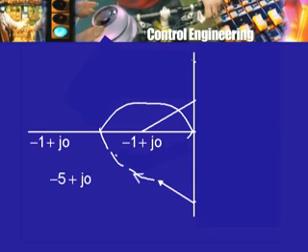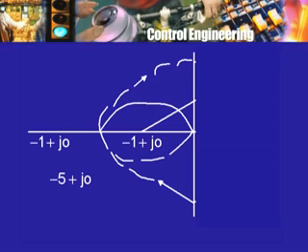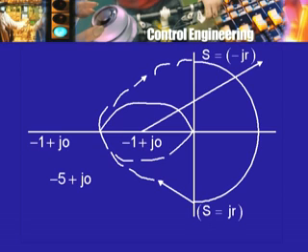So, this will be the variation of k by s g h at j omega as omega varies from 0 to infinity. That is the upper half part of the imaginary axis on our Nyquist contour gamma. Now, of course, for the lower part we are going to have a mirror image of it. So, I will draw the mirror image. So, it is going to be like this, and then it will go this way, and as before for very large frequencies the plot is very close to the origin. So, I can just show it by a big dot here. In other words, this curve is very close to the origin. This is what it is supposed to indicate.